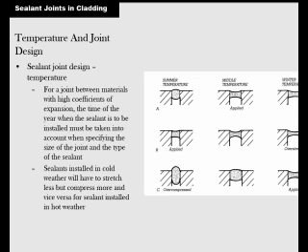Temperature: you need to take into account all the seasons when you're specifying your joint sealers. How will it react in the summer, how will it react in the winter? Make sure that it can handle the wide range of temperatures and weather conditions, and specify one that will.